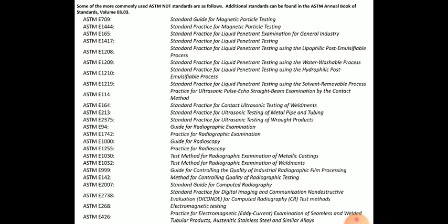And then ASTM radiography. You can see there is a difference between film and computed radiography. And there is always an ASTM standard, that is E142, the method for controlling quality of radiography testing. Then we are moving toward ASTM E2738, the standard practice for digital imaging and communication in non-destructive evaluation, DICONDE, for the computed radiography test method.